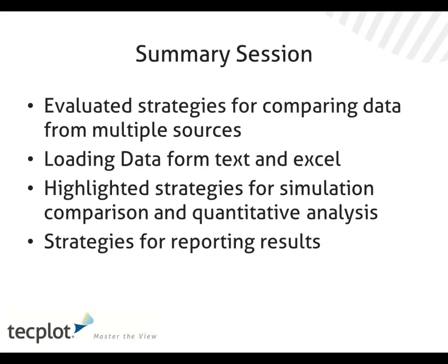Okay, let's see here. Plotting contours of multiple data sets in a single plot for comparison, and how would you do that? Like the example for string traces. Well, certainly you can do that. There's a couple of ways. You can read multiple data sets into a single data set if they have consistent data structures, mainly the same variables. Then they just become other zones within the same data set, and you can do plots on multiple zones with no problem.